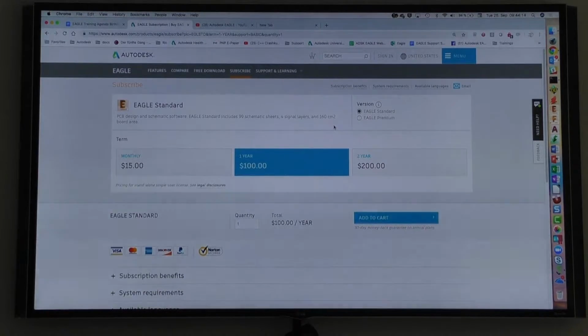There's another one in the schematics. You can draw a schematic which consists of a maximum of 99 sheets. I think that's not a limitation. The big one can do 999 sheets. I've seen schematics with 70 pages, it could happen, but that's not a real limitation. The limit is in the board design, of course. There's no limit in the number of components or something like this. It's really the board area and the number of layers you have.